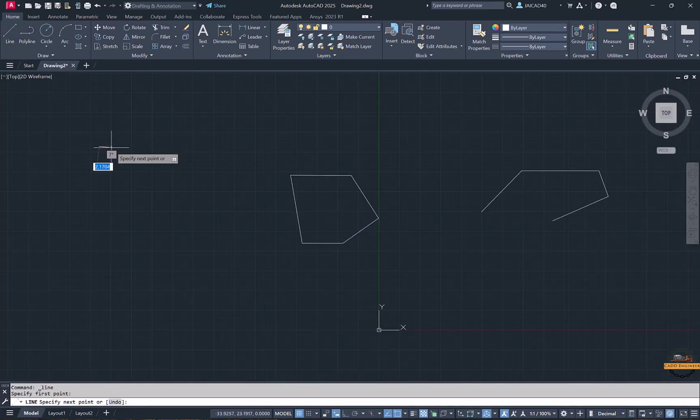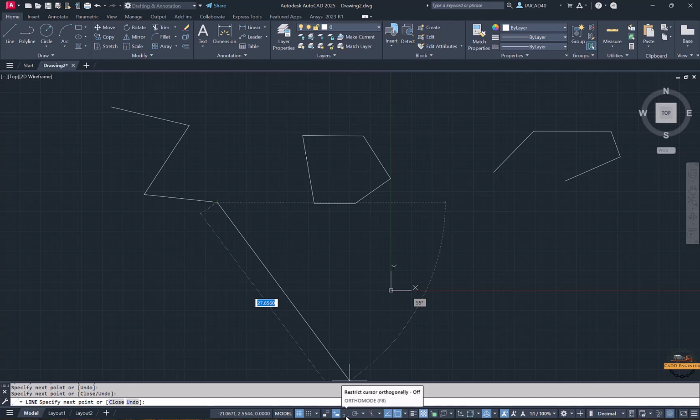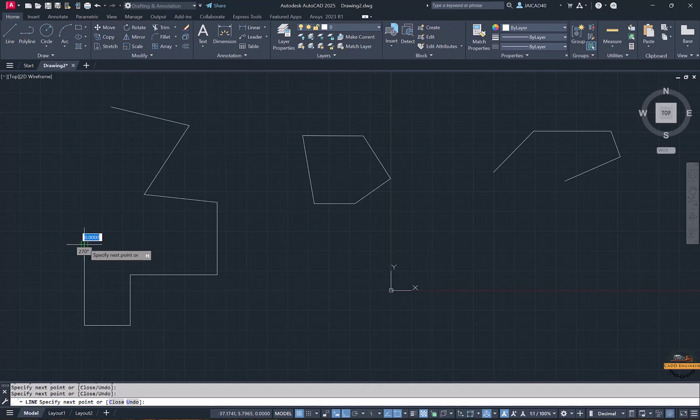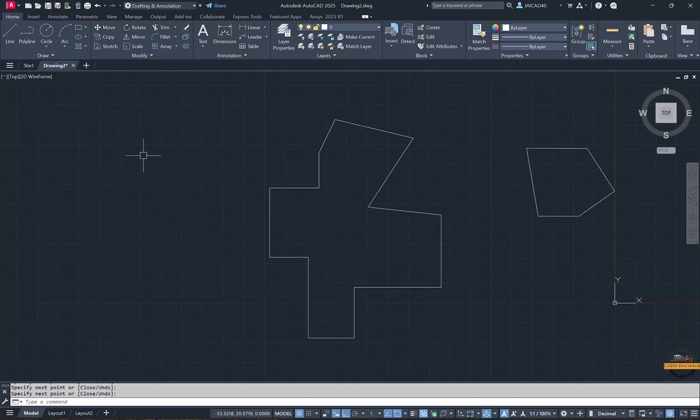Now initially the lines that we are making do not come out straight. You have to hold your mouse and drag the points, the green lines, then only you can make exactly straight lines. But in any situation where you want the line to come exactly straight, you can go to this option called ortho mode. You can click on that and it will be turned on. So like this we can make horizontal or vertical lines without any other things. Now that is about the line.